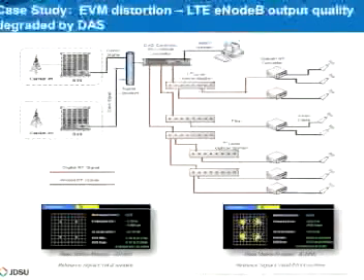This is a simple case study where we've actually seen, as we were demonstrating one of our products, and the customer's getting very excited about what they could see as far as visibility, again back to testability of a BTS. All of a sudden they stopped and they paused and they looked at me and said, "Can I also measure the DAS system?" Well, the first concern I had was, is it a neutral host? He said, yeah, but it's a stadium, there's nobody here right now, we can turn it off, we can make a connection into the antennas, and we have an attenuator so we're not damaging the test equipment, and we can look at what's coming on the other end of the DAS.